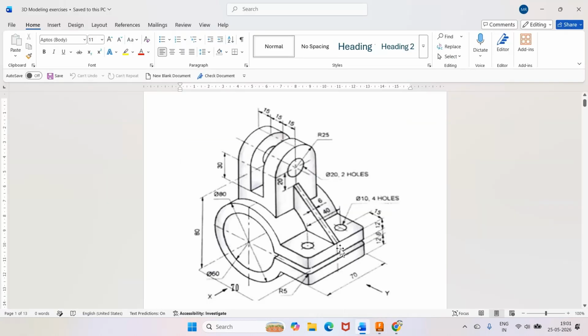Then I want to create this section. If you want to create this section, one way is to take it to the front plane and do it. That is not possible, basically because I have to take it from the right, and you don't know where exactly that point will be. Or one way is you just measure that, take the offset plane and then do it. This is one method. Or else what I can do is create it from the front view, and instead of taking the fillet radius, I will take this as the rectangle. See how it is going to be done.